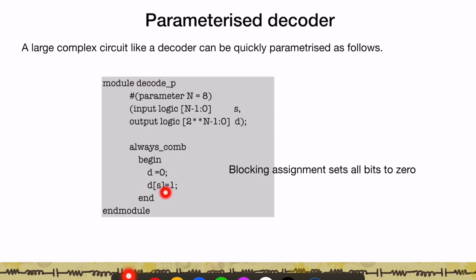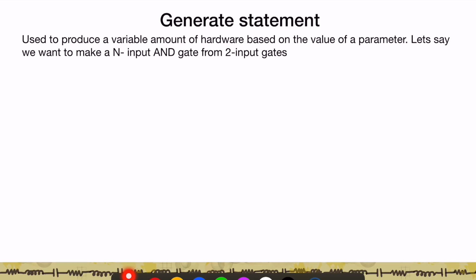So what you see here is d of s immediately will raise the asserted output bit to 1, right? And so this is a simple way. Now here, because I parameterize this, I can quickly use this as a 2:4 decoder or a 3:8 or a 4:16, whatever have you, by simply repeating this code and only passing a different parameter through its input, right?